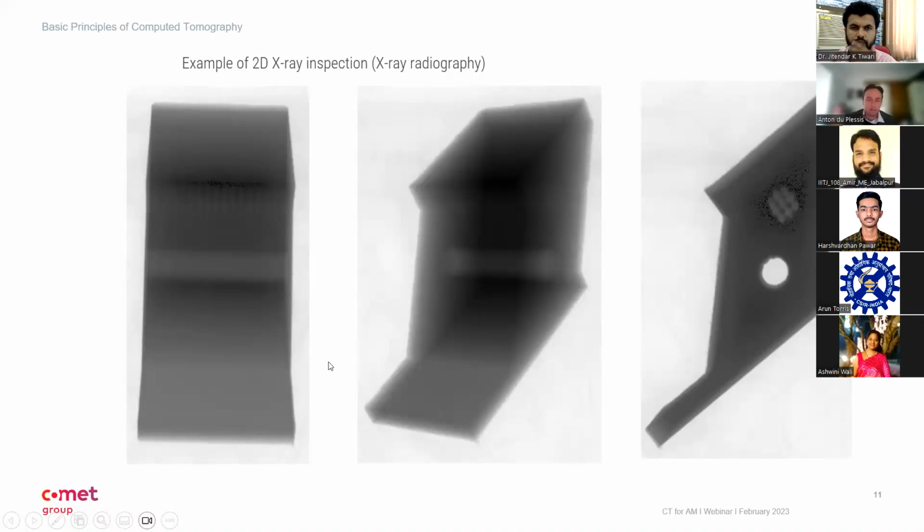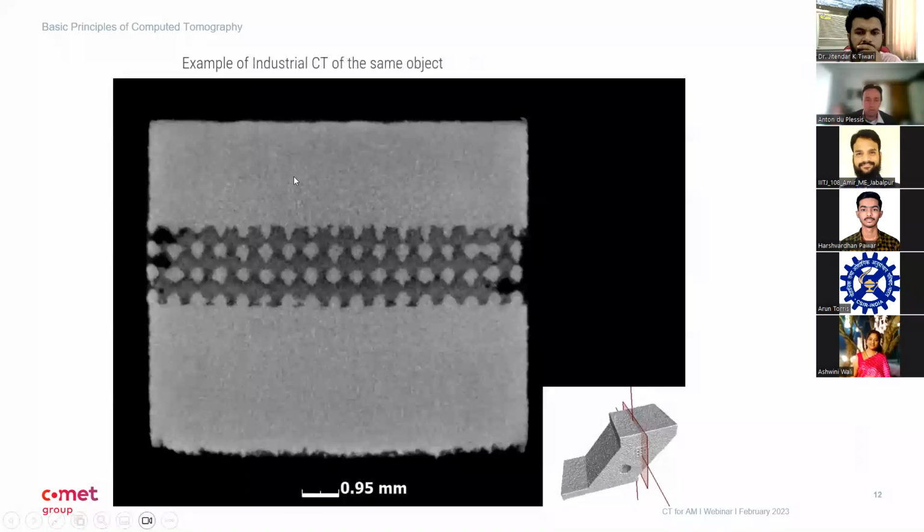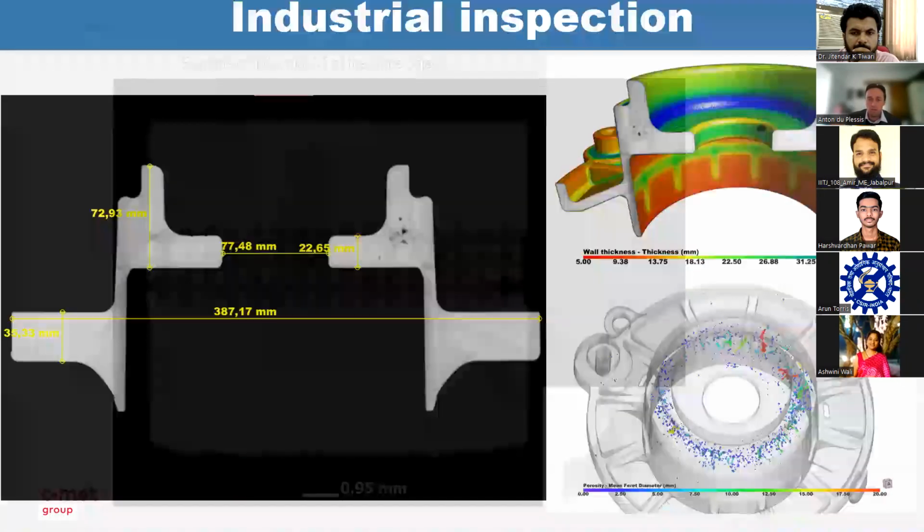If we take thousands of such images and make a CT reconstruction and then a cross-section through that, you see a lot more detail. If you make a cross-section in that red plane region there, you see some dense metal. The brighter parts are the dense parts, and the lower density gray is unmelted powder inside this. It's a channel with a lattice structure, and powders got stuck inside. So that's just an example to show the much more detail you get from CT than from 2D inspection.